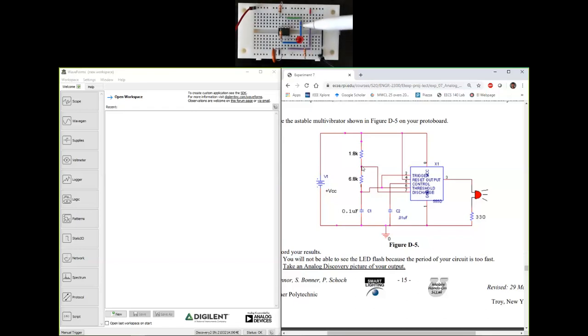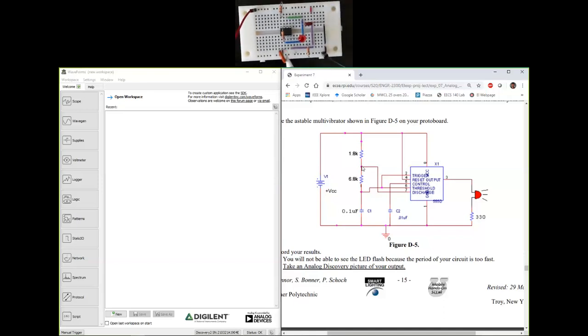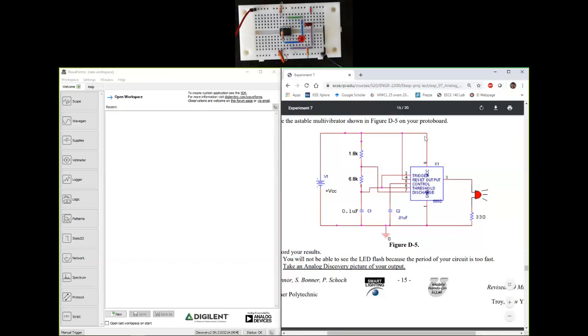What is left is pin 3. So pin 3 has an LED and a resistor in series connected to ground. So pin 3, long lead of the diode, the red colored diode here, the short lead or the negative side of the red LED is on the other side, connected to ground using a 330 ohm resistor, which has a color code of orange, orange, brown. So that's your entire circuit. So I hope that you are able to map the circuit diagram to each and every connection that I've shown you on this board.